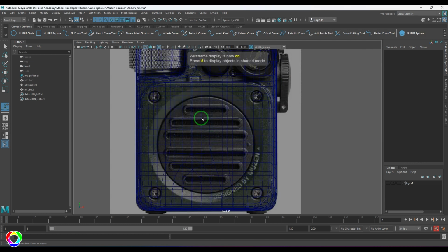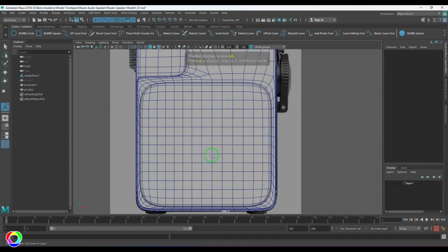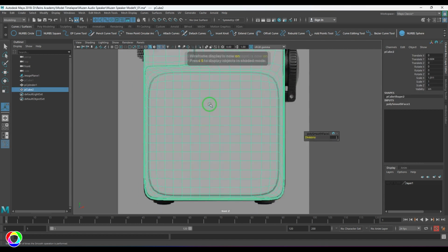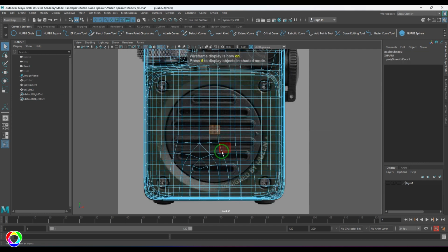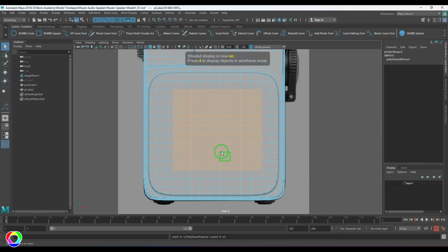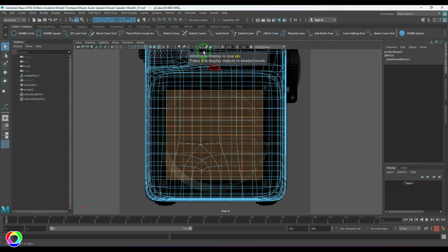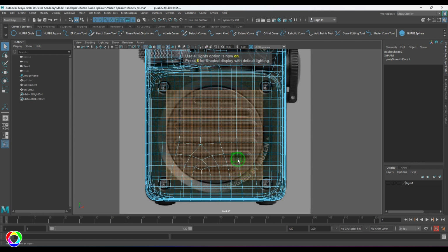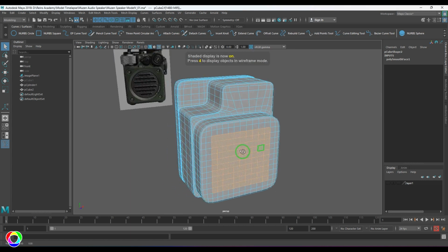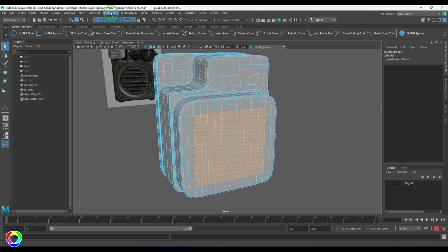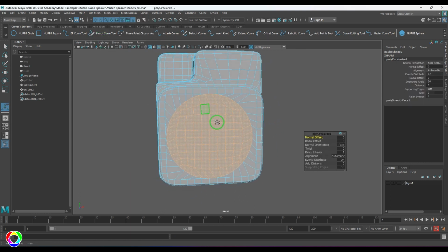Now I will select the faces and start punching the hole here. I'm just seeing whether these faces are properly centered or not. Okay, once that is done, I'll be selecting this, and then I'm going to apply the circularize tool.